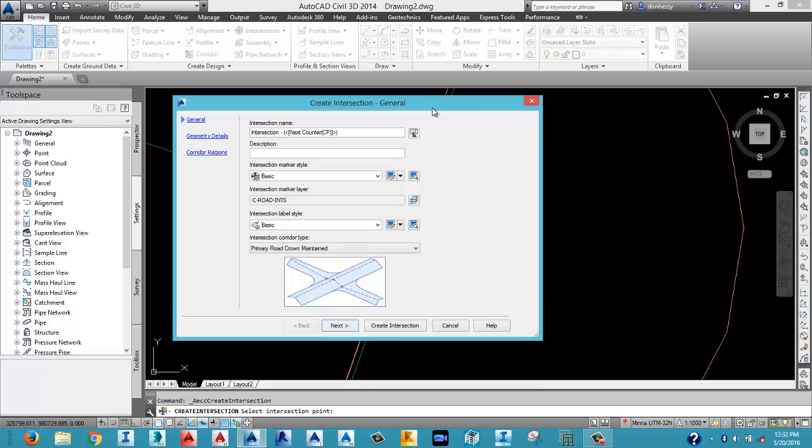You make sure where the alignment is. Okay, the alignment is there. There's so much information around this area. So if you have a challenge like what we have now, that we couldn't pick the point of intersection, what I always do is drag some labels out of that point so I can have a better view of my point of intersection. Like this one here, I'll just drag this label out. Can you see now? Once I drag out the label, call up my command again, create intersection. So I might be able to select that very easily now.